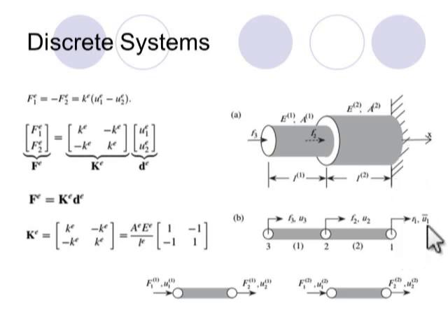So I put an overbar for the known values, and indeed I have the reaction force here. R1 is the reaction force coming from the wall. I just choose the direction as I did in statics and strength of materials, and I put all the forces from left to right. If the direction of the force is different, certainly the value that I will find will be negative.